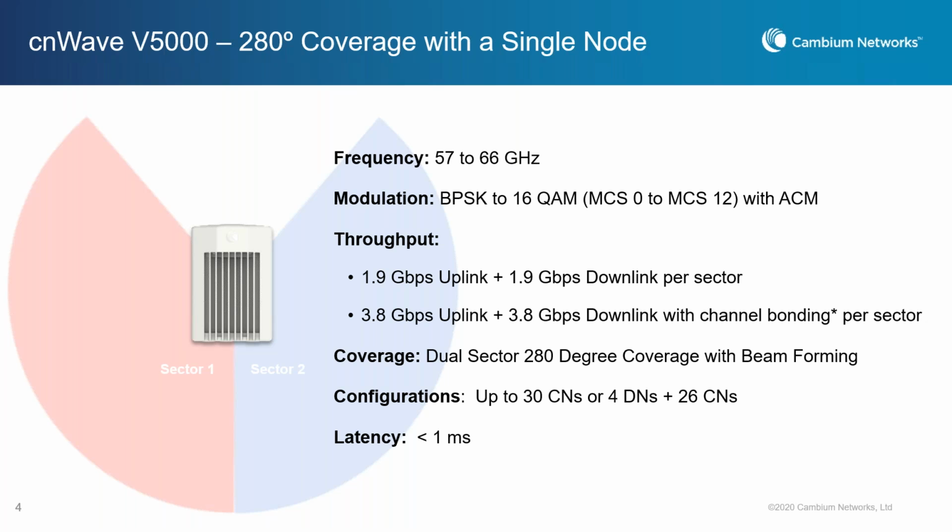So when we designed the radio, we designed this specific one with two sectors, and every sector with 140 degrees. When data transmits from sector to sector, like a relay configuration or a mesh configuration, you need data to transmit in different directions. With this configuration, all the sectors are in a single radio, so we remove the dependency on any external switch. We also simplify the power supply, which makes things far easier. Without channel bonding, we are able to support 3.8 gigabits per sector, and with two sectors, it becomes a 7.6 gig radio design.